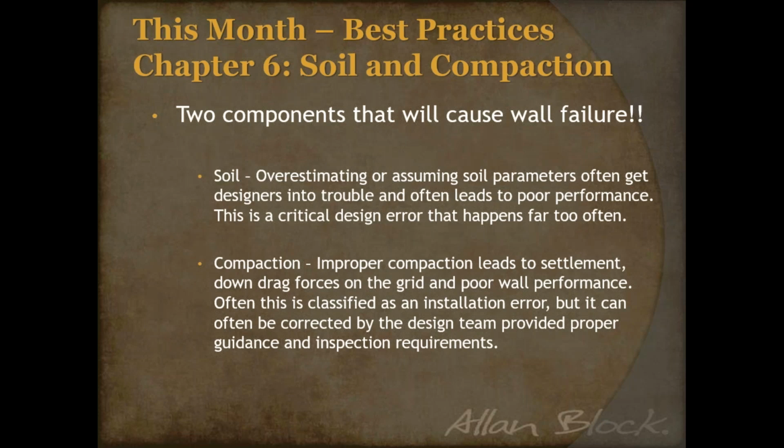Well, if the soil settles but the block doesn't, you get those grids that are forced downward behind the block, and you could actually overstress at that point, and those down drag forces could be a bit of a problem. So a lot of times we see people consider compaction as a construction issue, but I would challenge that we could actually, on the design side, be more proactive by calling out the specified requirements, whether that's the level of effort or the testing. And we'll get into that a little bit more.